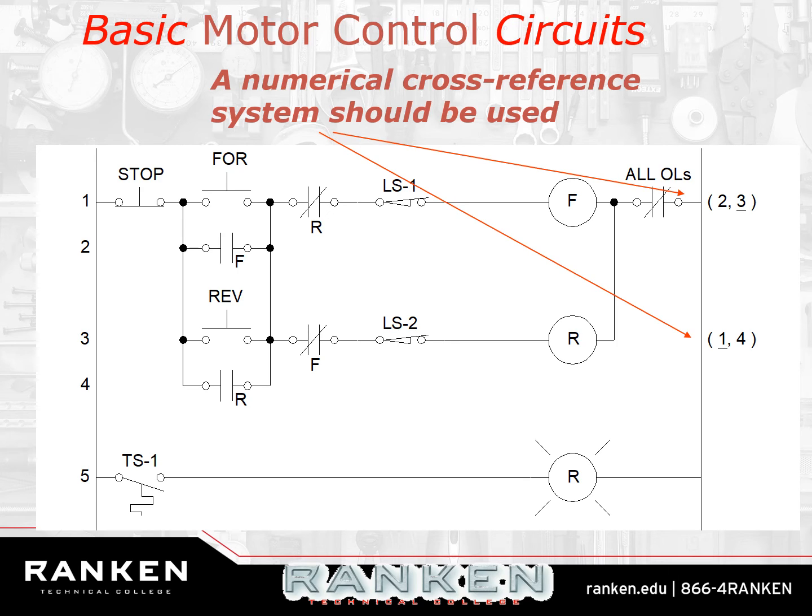Make sense? So I know that that coil is working properly because those contacts closed, and I can measure it. I don't know if physically that motor turned on, but I do know that the coil is working, theoretically. We're going to go over a lot of troubleshooting later on, but I can measure to make sure that coil is getting energy.